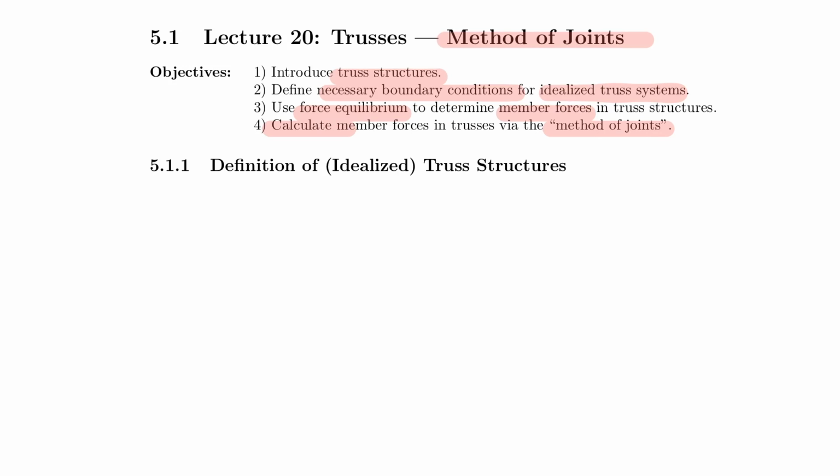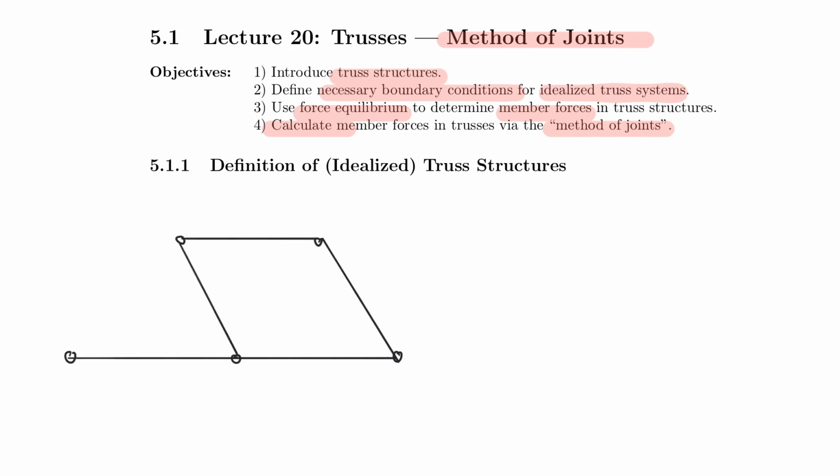So let's get started, and let's first draw actually a truss as we would see it in engineering mechanics. So for example, a very simple truss structure could look like this. And I'm actually making my life easier here by using these hinges. I will talk about that more in a second. But this could be your simple truss structure.